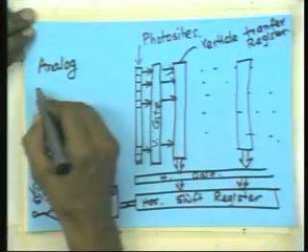All the vertical ones are transferred out to the horizontal ones one after another until you have a composite video signal. Only the charge at one photosite is selected. So each of them is sequentially put and you generate the signal. So it's basically an analog signal in both of these cases.